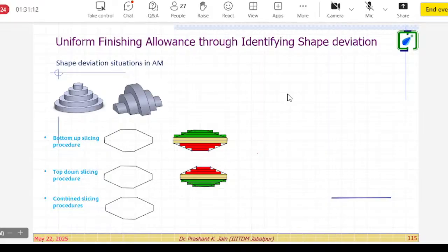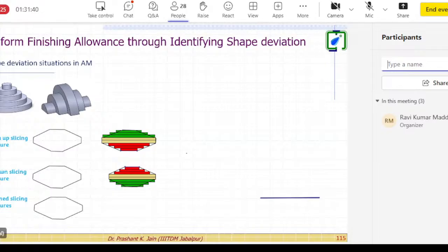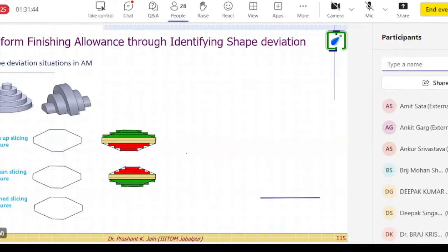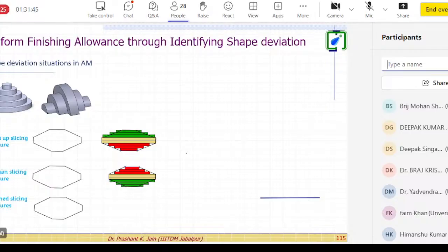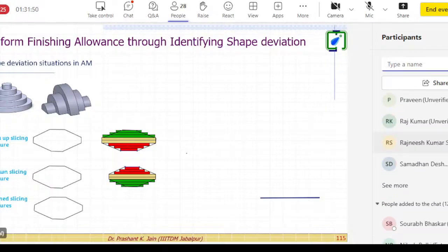What we want is either material that is less throughout the part, so that you can do some additional polishing or depositing more material on the fabricated parts, or extra material throughout the part. So what you can do is use machining processes like the hybrid processes I have shown to remove the material. Or another approach we have adopted is the selective melting process, where you can take the heated tool and melt the material which is extra. So that can be done, right?